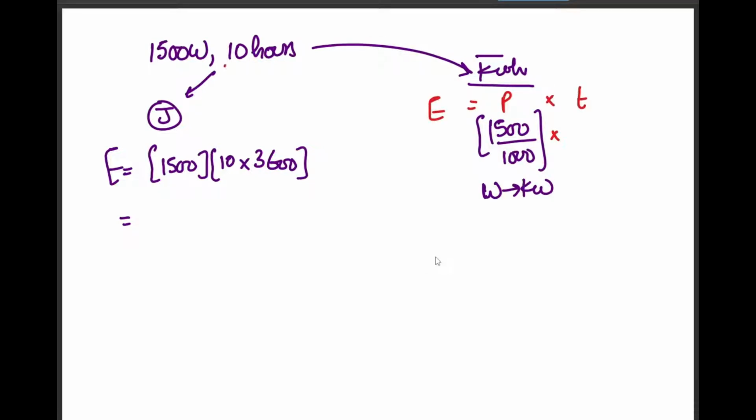So the time that it is operated for is 10 hours. And since the unit represents kilowatts and hours, I'm not going to convert hours into another unit because hours is itself part of the same unit. So that will be 1.5 multiplied by 10, that is going to be 15 kilowatt hours of energy. This is what your electrical company bills you for.